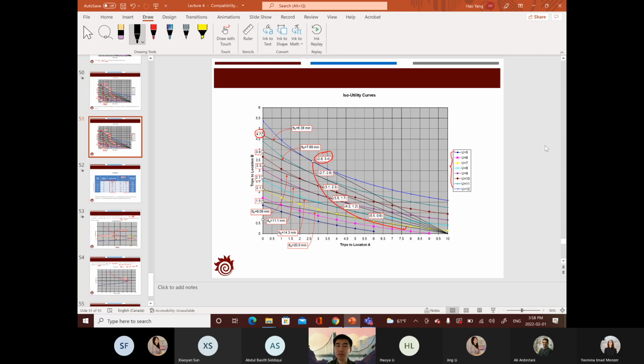The fundamental diagram is applied for you to determine the supply curve for a transport system. And they will also tell you how to use the isocost curve. The isocost curve here is applied for you to search for the demand function, the demand curve. And once you have supply and demand curves, you need to combine them together. The intersection is the solution you need for similar problems.